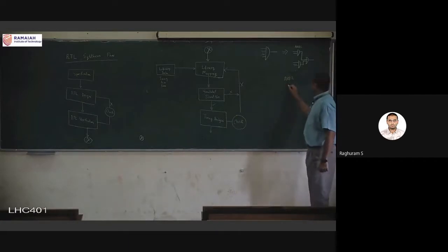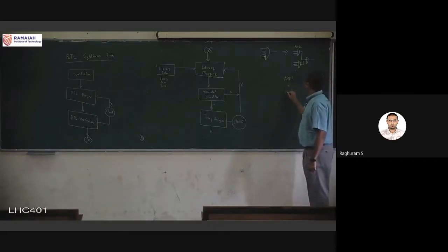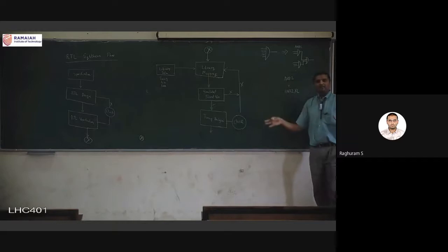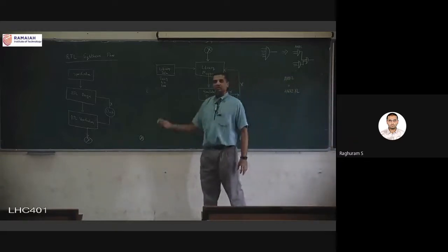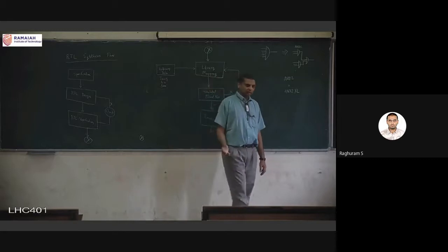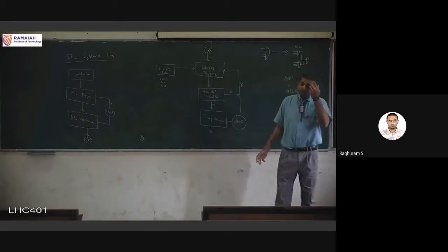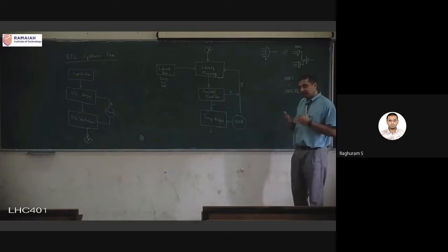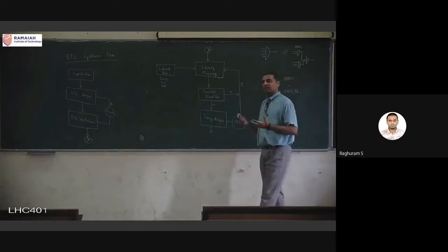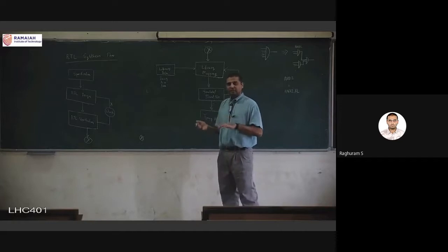So I might go from AND2 to AND2 extra large. And as we will see in the third or fourth unit when we are talking more about time, if we make the size of the gate bigger, it becomes faster. Why? We will see more detail in the third or fourth unit.